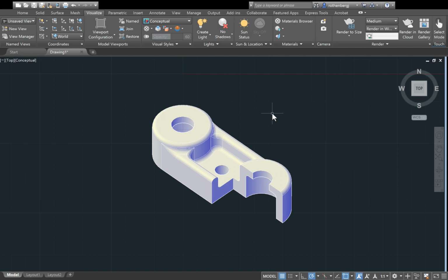Thank you for watching video 3 of 3 of how to construct the 3D saddle block broken out sectional. In this video, we took the 3D model that we made in the previous video and used the fillet tool to smooth out most of the edges and used the box tool to take out one of the corners to actually turn it into a broken out sectional.